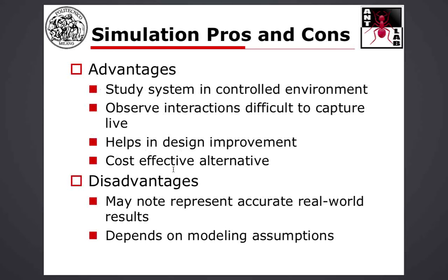At the same time, we have several advantages in simulating. We can study the system in an environment which is controlled by us, meaning that we can set up the radio links, for example the expected packet loss between sensor nodes. We can inject particular types of packets in the network. We can set some conditions as we want in order to see whether the system reacts properly or not.